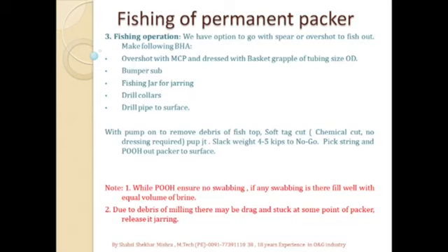And if we have followed the tubing joint into the overshot, we will see an increase in pump pressure. At that time we'll stop the pump and observe and bleed off the pressure. Then further slack the weight 4, 5, 6 tons and see the travel till the no go.